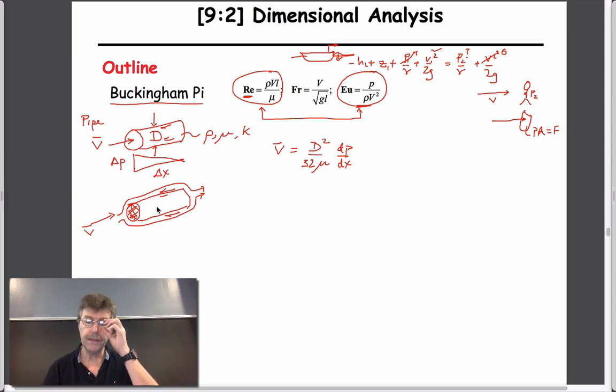And it's the same problem in that, in the same way that we talked about these important non-dimensional parameters, the Reynolds number is the one that figures out exactly what the flow regime will look like, and the Euler number is the one that will be able to, bless you, define the magnitude of the forces that are applied on it, which we typically want to know. Whether the forces are drag, if they're aligned along this tube, or lift, if they're perpendicular to it, as in a wing, that's what we'd like to know. And so if we've said that these are the important parameters, the question is, can we rearrange this expression in terms of those important parameters?